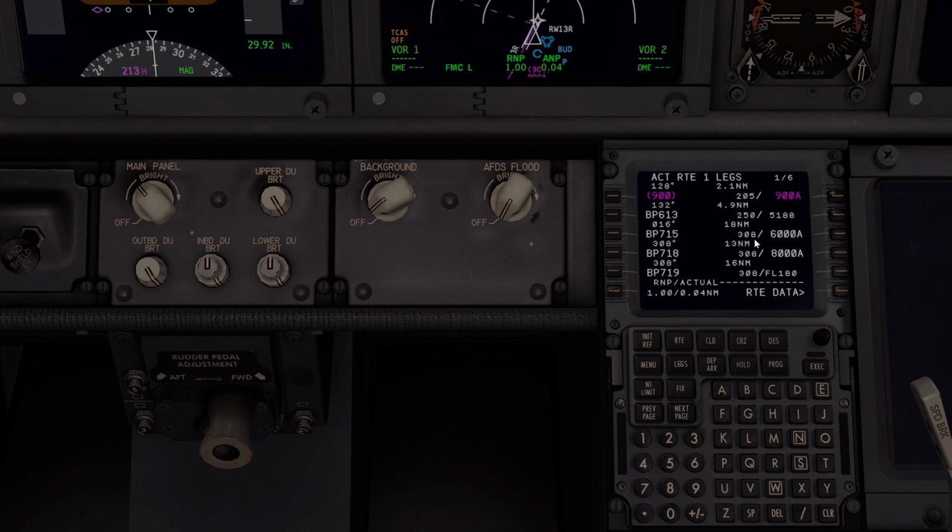Here we have all these values filled in. This means that we did a good job. Everything is filled in as it should be, and the computer was able to calculate all these intermediary values which are not in the flight plan, like 9000 and 6000. These altitudes were pre-programmed and they are mandatory, and they are in the flight plan. And in between there is this altitude in small font. This is a proposed altitude or calculated altitude by the FMC.